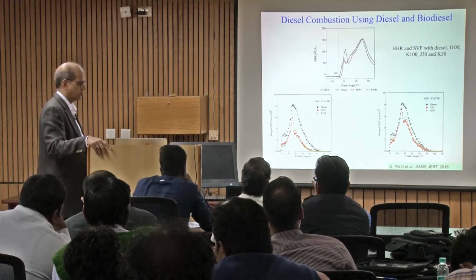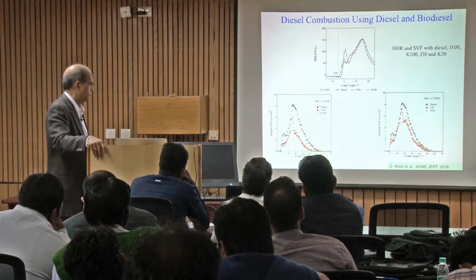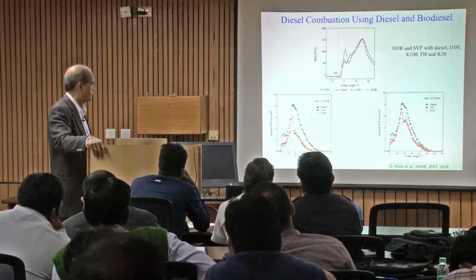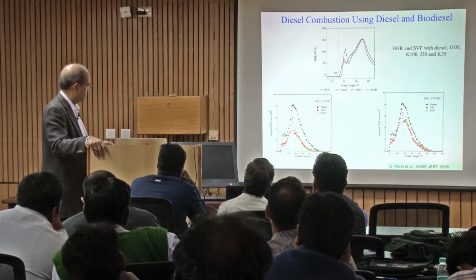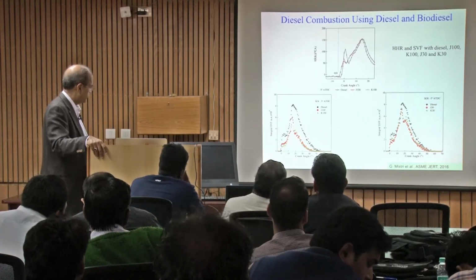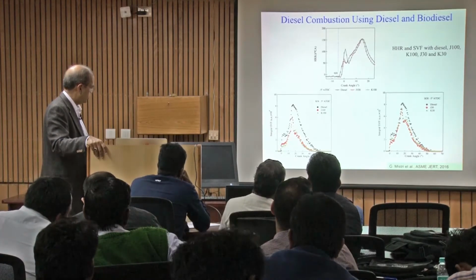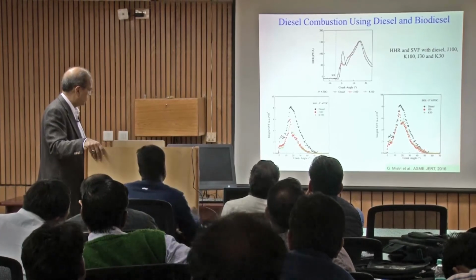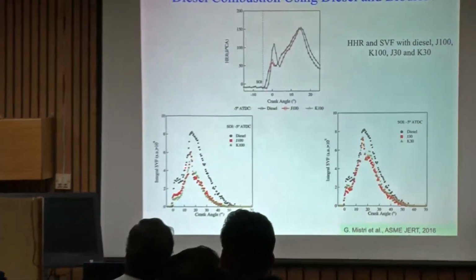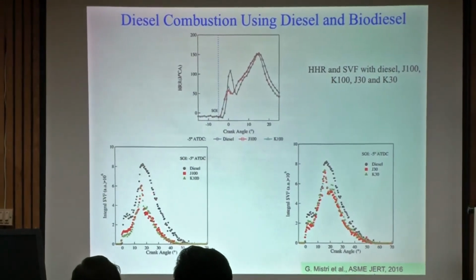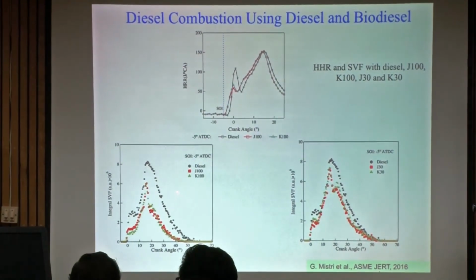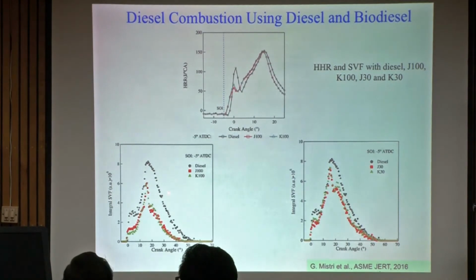Yes, finally it is oxidized. But in that region of 10 to 20 degrees, it is high in the diffusion burning region. It's being formed, it starts. So you see, this is the premix part where it's formed, but then it keeps forming, because there are those intermediate hydrocarbons which are producing soot.